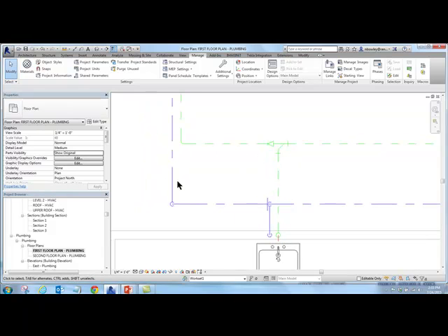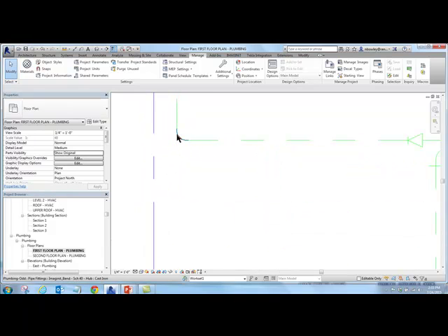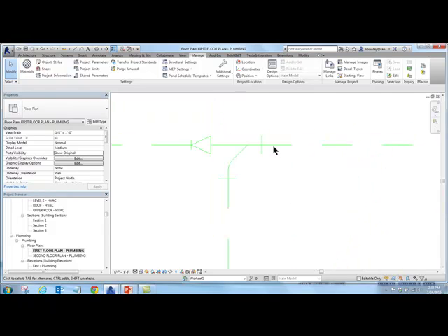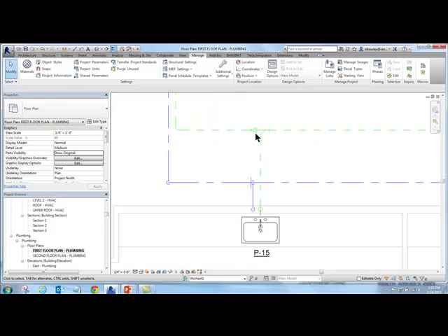The reason I like my annotation scale to be on is that if I have a long sweep elbow, say on a 12-inch chilled water pipe, ideally you would show something that big in double line, but that way you still see the long sweep of the elbow, even if your old drafting standard was still a 90 degree. And if you have combination tees for sanitary like this, they still show up nicely. They still show up at the true size, as opposed to being blown up. Like this tee here might be not realistic at the moment.